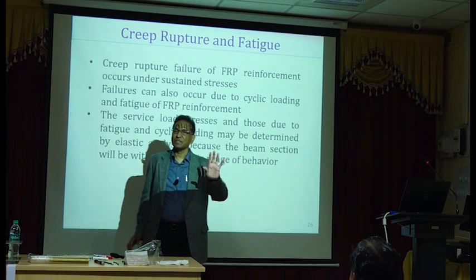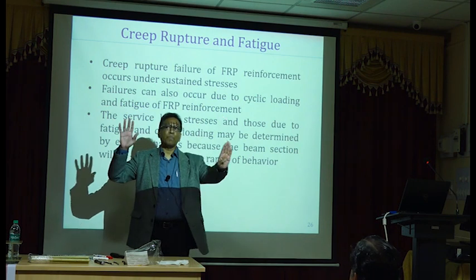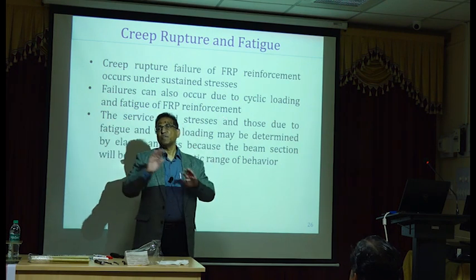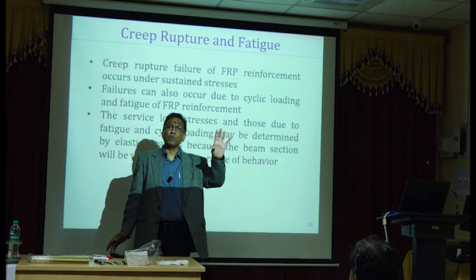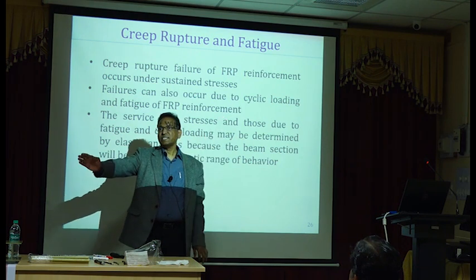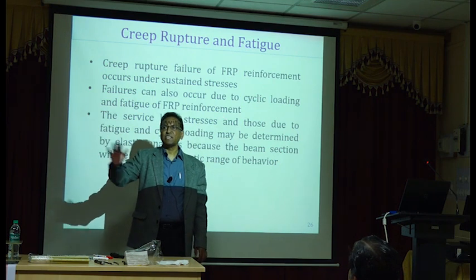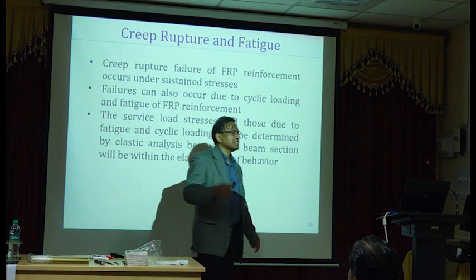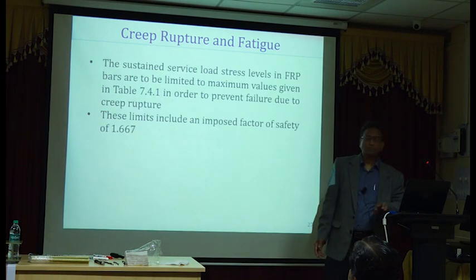And we have maximum limits, so you compare the two. If the service load stresses due to sustained load or fatigue are less than the maximum allowed, then we are safe. If not, we have to change the design.